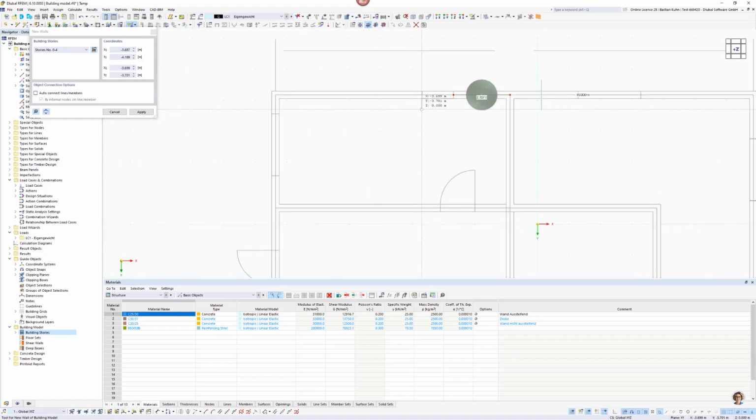You see, with the building story or with the building model add-on, there's already coming the information of the mass of my structure. So right now I define two walls or two parts of the wall, and I have a complete weight or a mass of 9.72 tons.